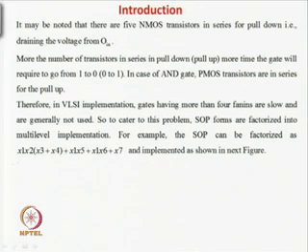Here the minimization is that we have to make it in a multi-level format, that is, take the sum of products form or the product of sums form, and then implement it in multiple levels. So, it will be factorized, and the factorization should be such that the implementation has the minimum number of gates, that is, the minimum number of terms, and the number of literals in a term should also be minimum, so that there is a minimum number of fan-ins for the gate. This is the same as your 2-level minimization, but here the levels will be much more in number.